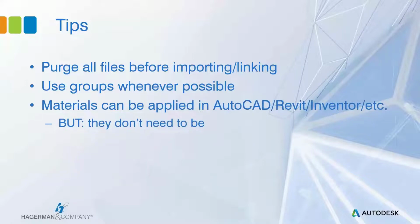All of the authoring tools that we use every day, they're capable of adding materials, and they transfer to Max just fine. The Autodesk products all rely on the same material libraries. However, it's not necessary to add them in the source models. In Revit, sure, materials are a big part of Revit, but in tools like Plant 3D and Advanced Steel, the focus is not on the materials in those products. So it's best to ignore them until you get into Max, and then use the material editor in Max to apply those.